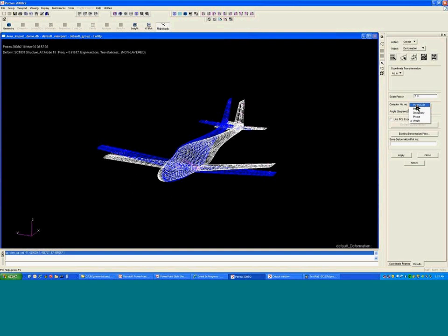It doesn't always make sense to make a deformation, but it will deform the grids by the magnitude of the complex number, by the real component, by the imaginary component, by the phase component, or by the deformation associated with a particular phase angle. Of course, you can also do marker plots. So maybe for the imaginary component, you would rather see a marker plot or a fringe plot of the imaginary values. So all of that's available.